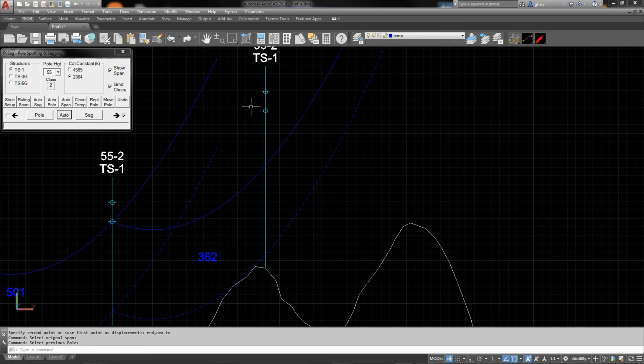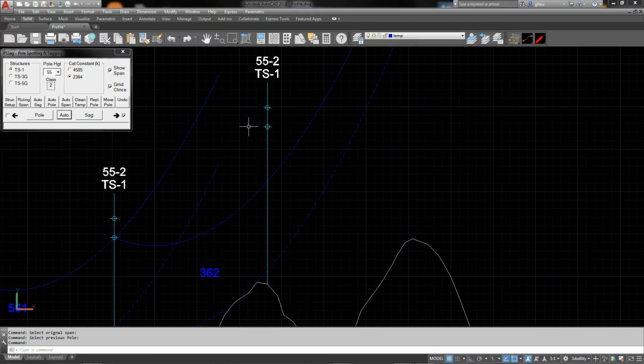And we see here that pole is much taller than we need there, so we're going to go back and reduce the height on that pole. We possibly could go to a 40 and still get our clearance in this span, but then we've got to deal with this other hill coming up, and so we're going to replace it with a 45.